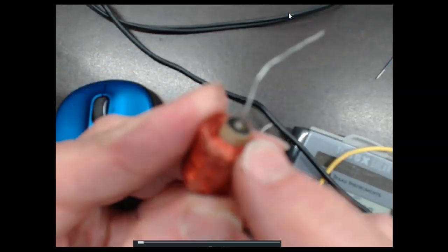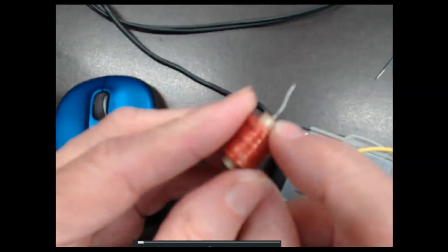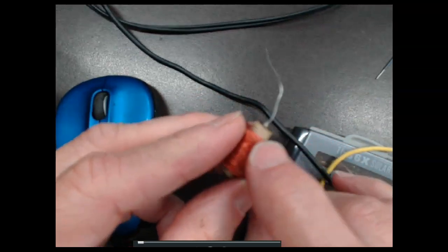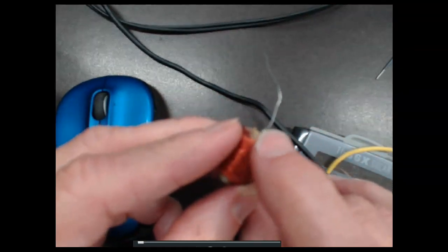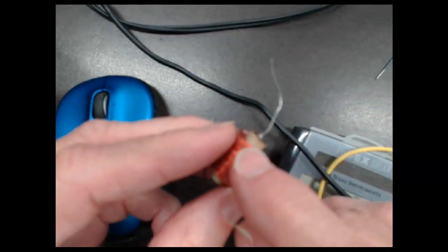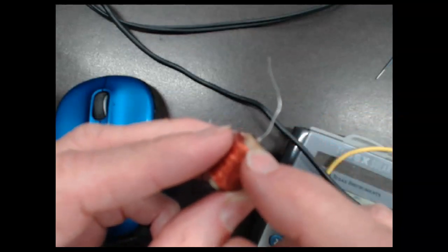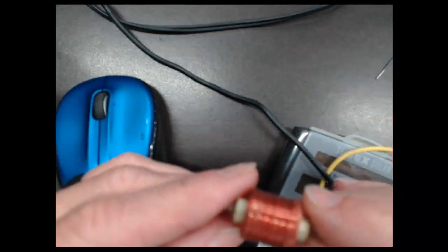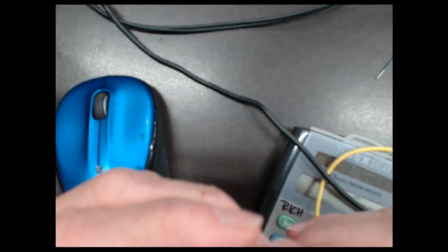They're wrapped around a ceramic spool, and that little tiny wire comes over here and solders onto that. What happens when we get these things out in lab is they break that little wire. Very, very small. So a quick check for an inductor is just to measure with your ohm meter.